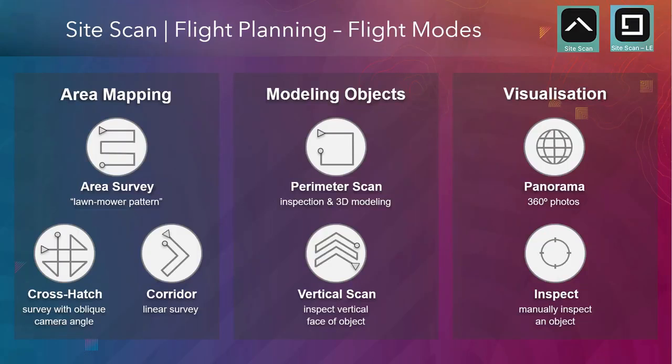When planning, there are three principal flight modes that you would look at. Mapping for ArcGIS ready products. There's the traditional area scan, for aerial photography, digital elevation models and digital surface models, point cloud and contours, and you do it with a vertical gimbal with an 80% forward overlap and a 70% side lap. Most of your GIS ready products will come in this flight pattern.